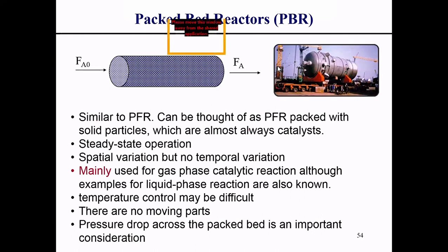And this is the packed bed reactor. It's similar with the plug flow, but we have something that you put inside it, whether it's a catalyst or adsorbent. The assumption is similar: steady state, spatial variation but no temporal variation, mainly used for gas phase catalytic reaction, although examples for liquid phase reaction are also known. There are no moving parts and there is pressure drop across the pack. That is an important consideration.